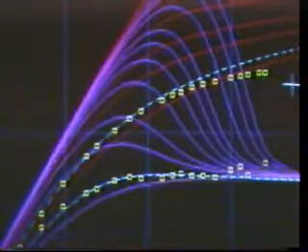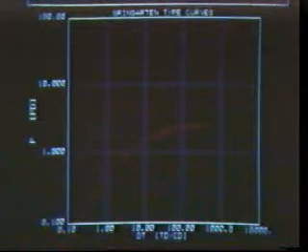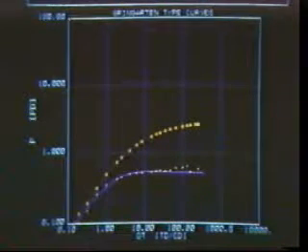When the proper match is obtained, the pressure and derivative data will lie on the corresponding curves at the same time. If the best match lies somewhere between the type curves, not to worry. The computer will generate a unique type curve for both data and derivative curves. Ultimately, the values obtained from a type curve analysis should show close correspondence with the values obtained from the conventional Horner analysis.